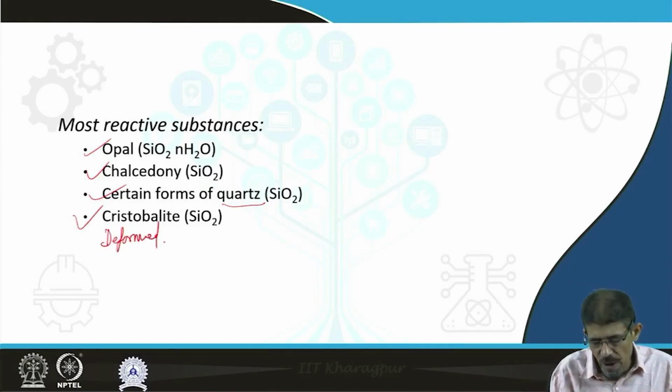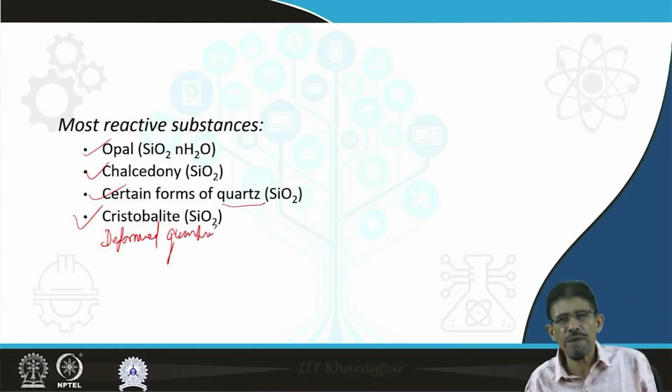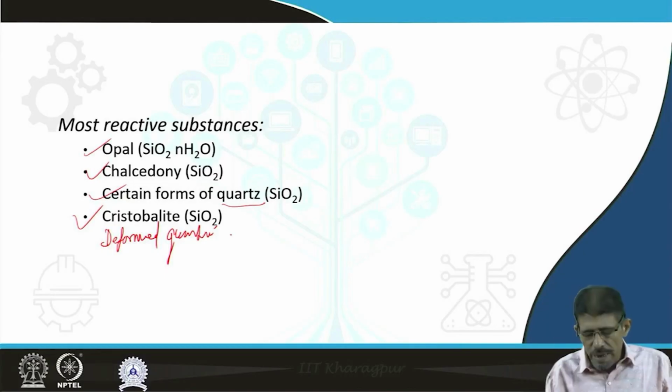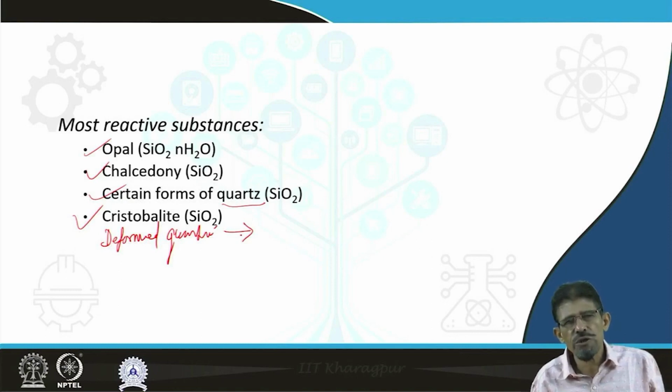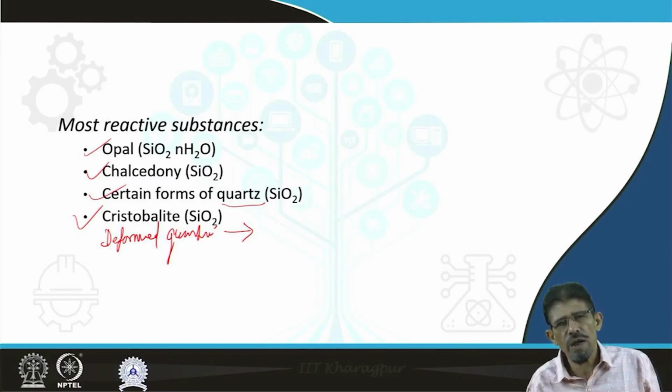Deformed quartz means quartz associated with a metamorphic or tectonically deformed zone. In the microscope, if we observe undulose extinction, it means the quartz is deformed in nature. So avoid such aggregate in selection, if the aggregate shows quartz grains with undulose extinction, as such aggregate may be problematic.